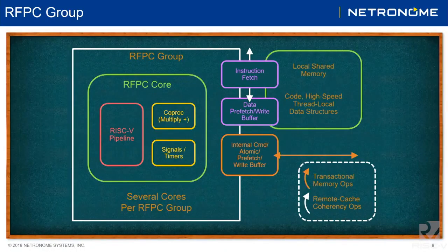We evaluated several different cores. We settled on the RV32IMC and wanted some additional features for bit manipulation commands. We utilized the custom instruction to manage the memory binding operations.